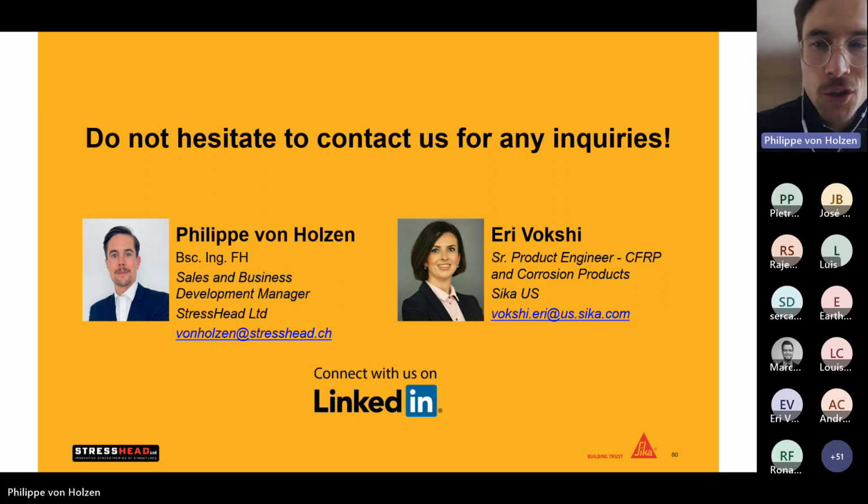That's a great question. Thanks a lot. So there are several ways how we work. We have standardized anchors, where we have already made all the calculations. The only calculation left is the post-tensioning force that we need, and whether the structure will be capable of absorbing this post-tensioning force, let's say, with this shear pin.